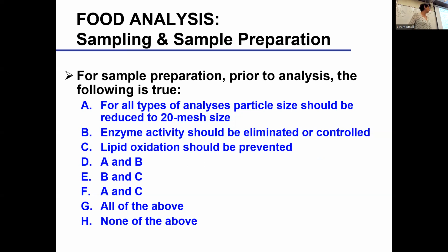Yes, Sarah? That's right, so that's like the sifter grain size that you order. Yes, it is, but if you want to be a little bit more specific, when we say 20 mesh, that means there's 20 openings per linear inch.